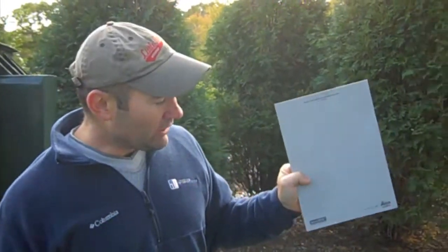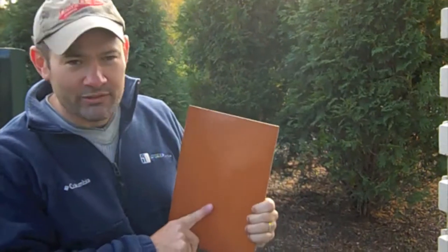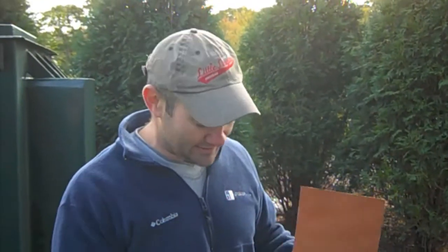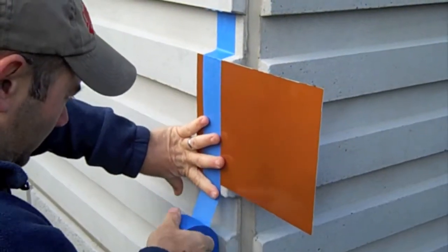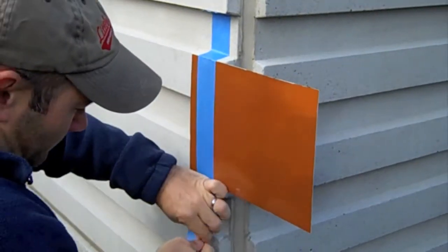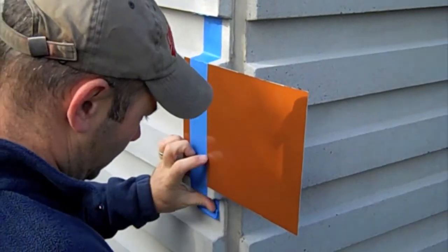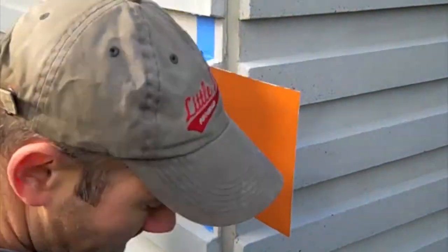So when we're capturing the exterior of a building, I like to hang a target on one edge. So what I'm going to use is a target provided by Leica. You have a sort of flat matte side and a highly reflective side, which allows you to get long distances. I also use painter's tape. Why? It's quick release, it doesn't leave anything on the building. So now we're ready to measure the first wall.